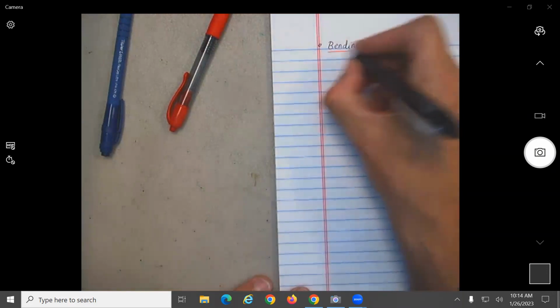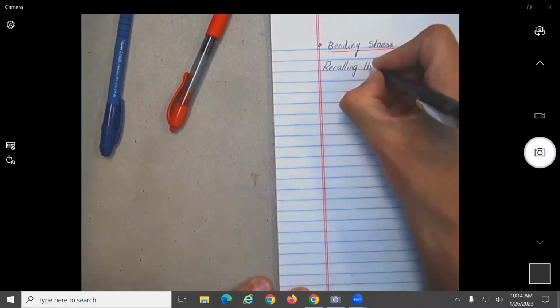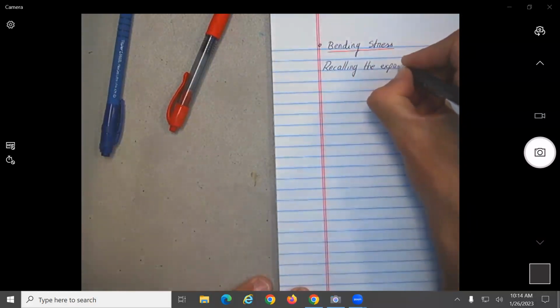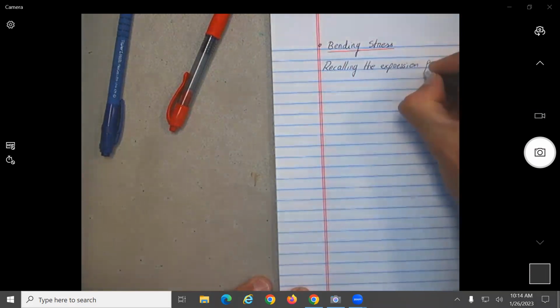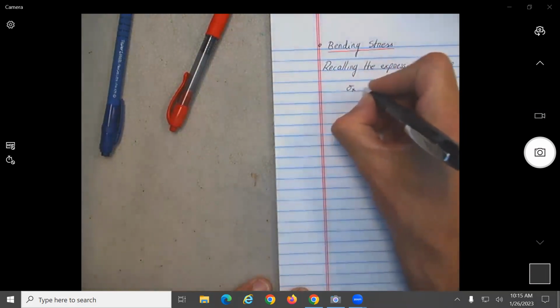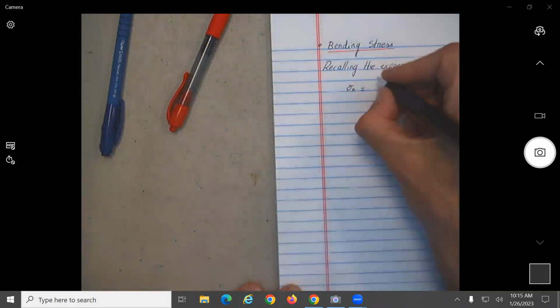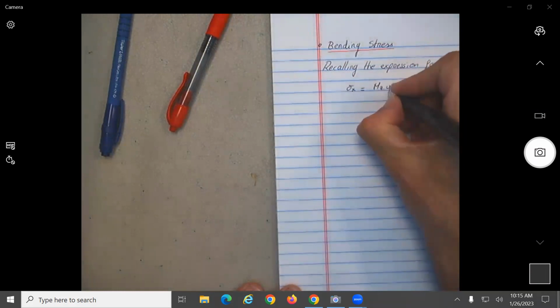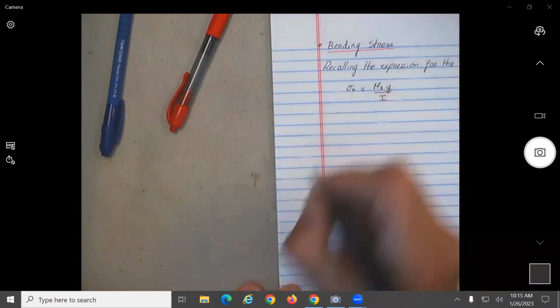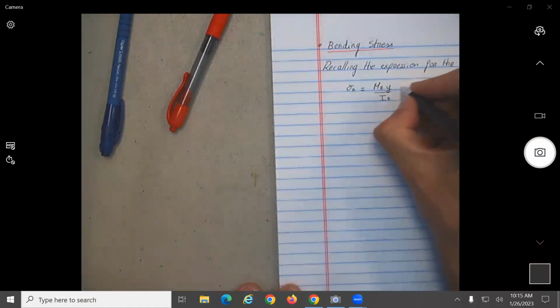We call in the expression for the bending stress. In this case, remember, it will produce a stress in the x direction. I'm not going to put the sign, so one would be Mz times y divided by which one? Iz, perfect. And here I'm going to put plus